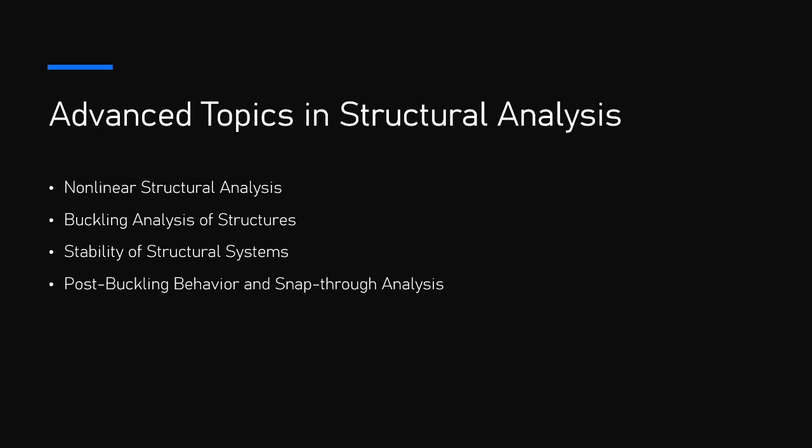2. Nonlinear effects. Structures must be analyzed for nonlinear effects, such as material yielding, large deformations, and buckling under realistic loading conditions. Nonlinear analysis tools are essential for understanding the complex behavior of structures, especially in regions where extreme loading or large displacements occur.